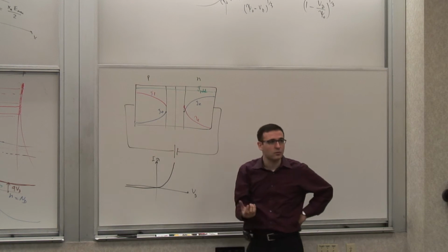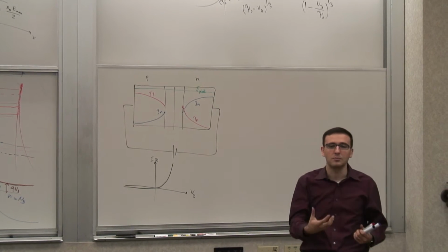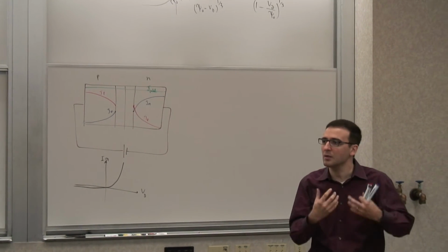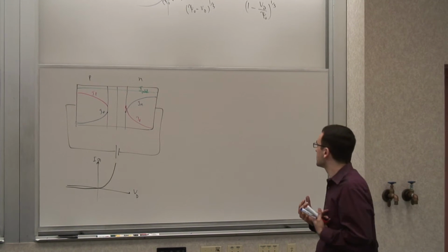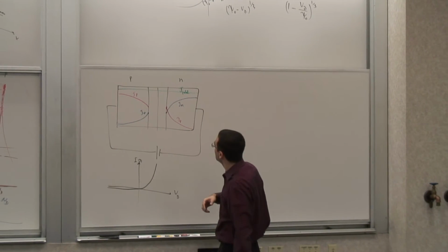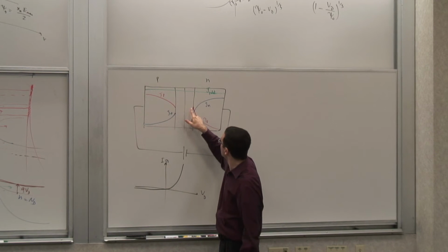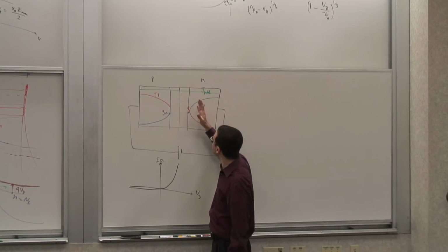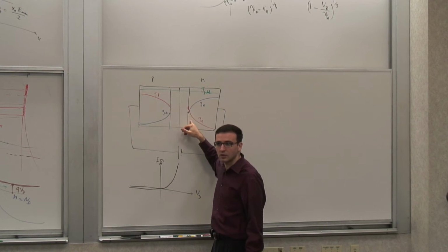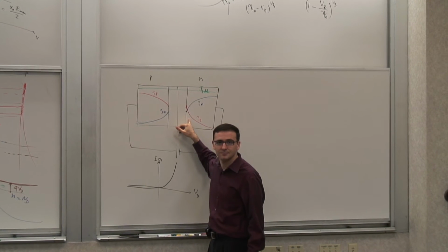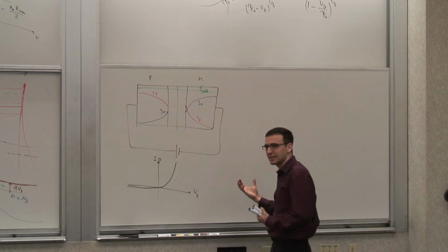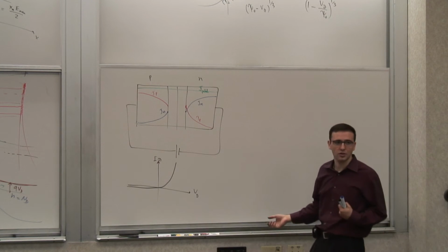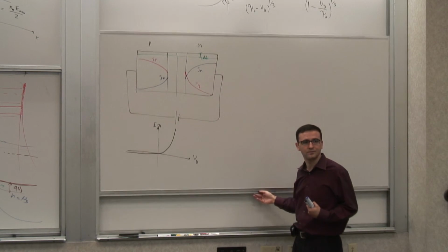And the way to capture these minority carriers would be to capture them into a region where they are not minority carriers anymore. Right? So for instance, if I want to capture these holes injected from this side, I need to have another P region close enough before they are all recombined with the ends. So that's the basic idea behind the bipolar junction transistor, or BJT.